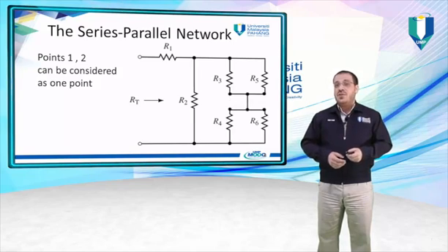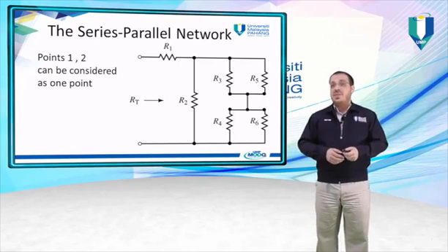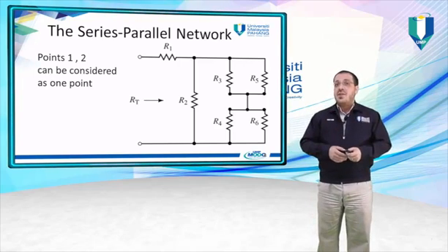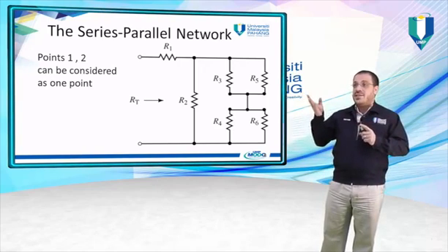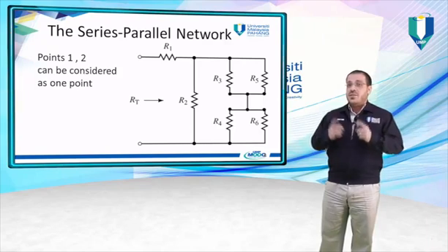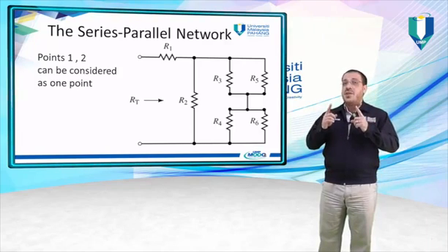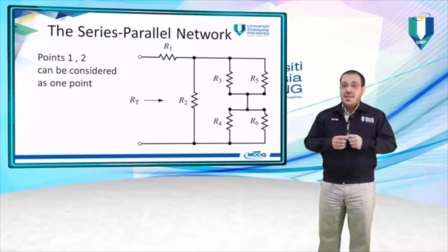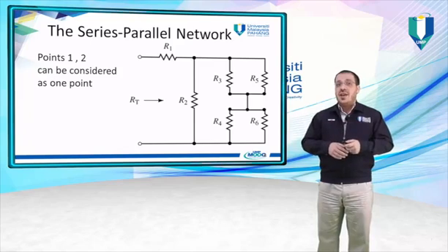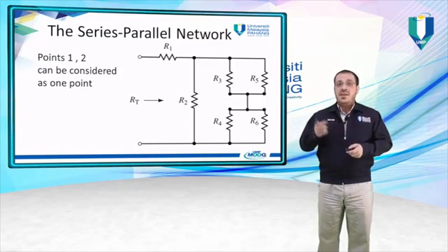Now, if you look at this circuit, I think you can imagine it better. It's clear that R3 and R5 are in parallel, and R4 and R6 are also in parallel. So the result of R3 parallel R5 and R4 parallel R6 will give us the correct answer. The final relation is that all are in parallel with R2, and then the result is in series with R1.